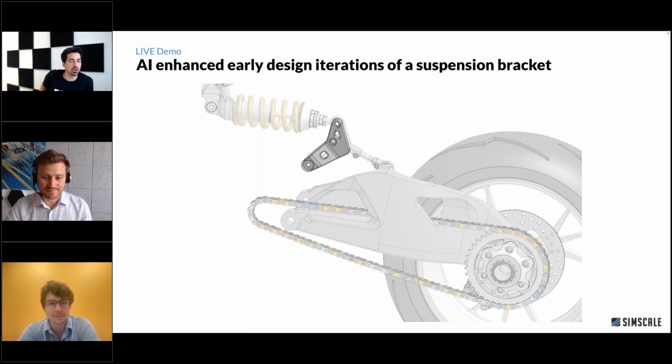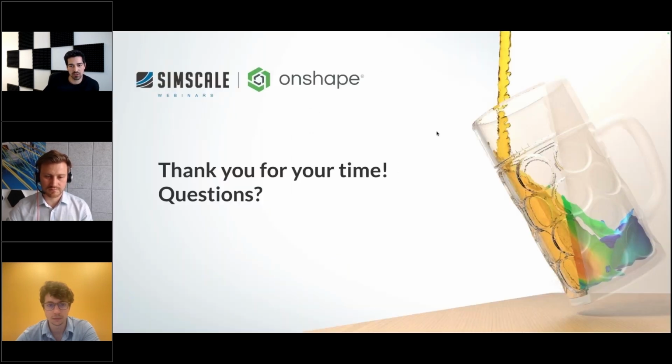Yeah. So we're currently going through all the analysis types. Steve has shown you in the simulation setup, we have about 13 different analysis types. Although the method itself is agnostic, you just need to still enable the process so that these results are understood and can be trained. Currently we're working on the conjugate heat transfer analysis that will be enabled toward the end of this quarter, beginning of next quarter. Then you can really train coupled fluid thermal analysis with the structure and the fluid inside, predict the pressure and the velocities in the fluid, but also the temperature distribution in the solid, for example.